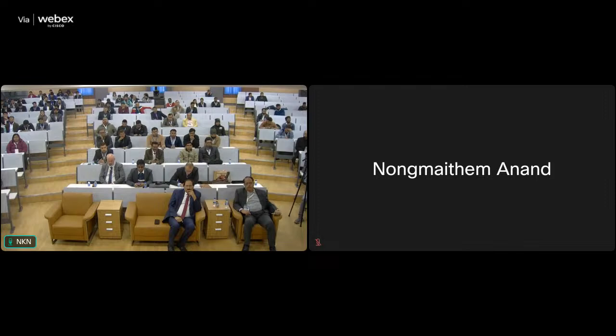Now, what should be the modified Q then? Because I have shown in the earlier slide the modification in various parameter ratings. The original Q value 1 to 4 in first column, the modified Q value can be 3 to 10. So 1 changes to 3 and 4 to 2.5. So as the improvement is there in the Q value, the effect is less. With this logic, this has been studied and prepared. Now, similarly, in the good rocks, 10 to 40, the modified is 20 to 40. So in case of 40, no influence of pre-grouting, rock bolt full column grouting is expected.